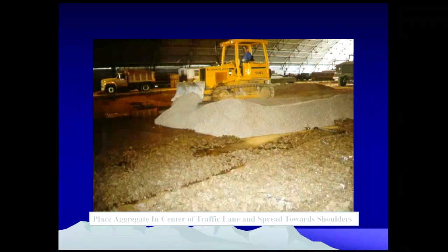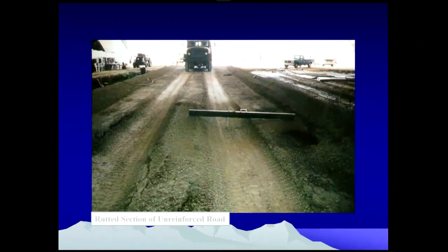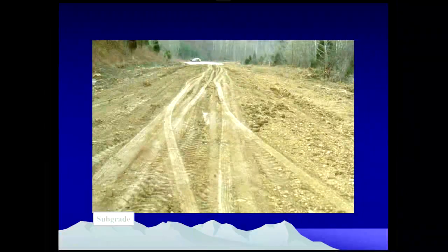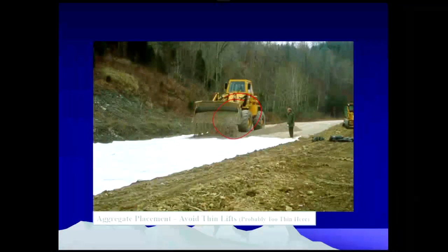And these are all the other kinds of works in the laboratory. You can see the laboratory works, connected sections of unreinforced sections. And finally, this is our subgrade. I am placing a geotextile over it and placing the aggregate, and as I said, when you are doing this, you should avoid thin lifts.